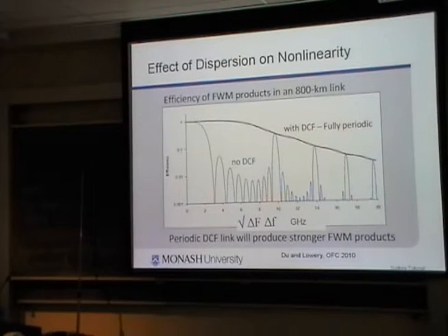Really, that's a little frond that comes around. So each one produces its little frond, like that, and then, oh, this is 8 spans. It comes back to the origin, and that produces a null. So the four-wave mixing at that particular frequency over that number of spans does that.